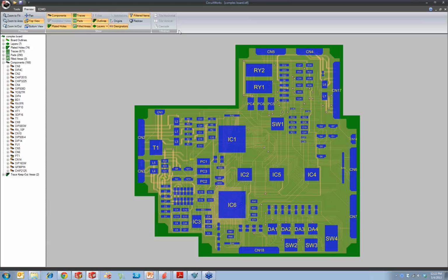But if you notice this, if I were to build this board in SolidWorks, it might take me 5 or 10 minutes of processing time on my computer to actually build this automatically, because it's a very large board with lots of features and all the traces and everything. Maybe we don't need all of the information. We just need some of the information to come in. So that's what the Tools menu here is for at the top of my screen.